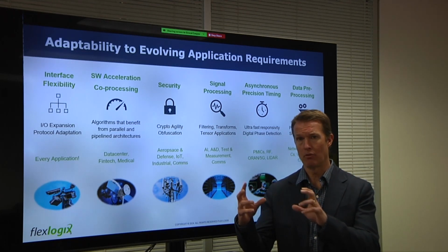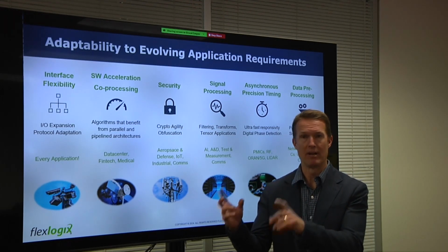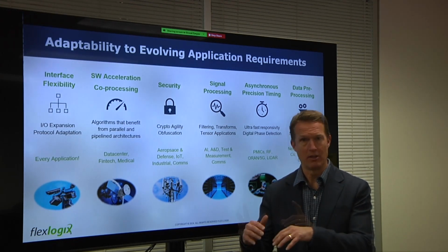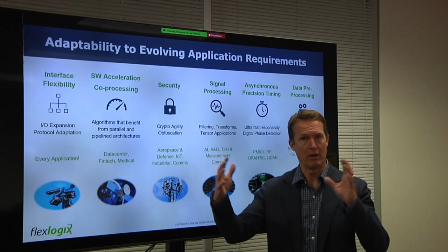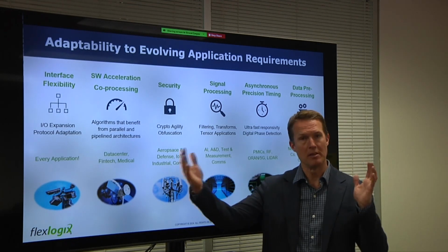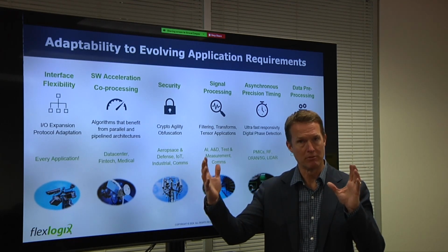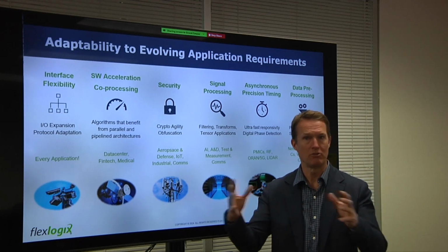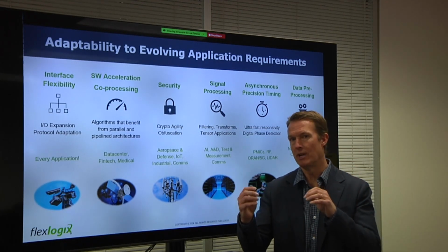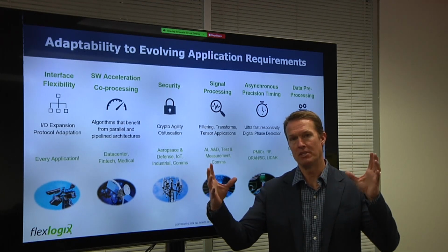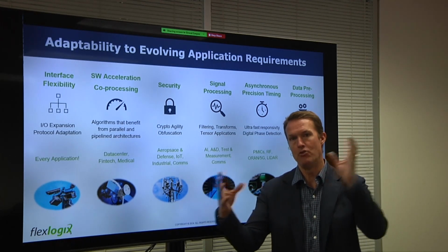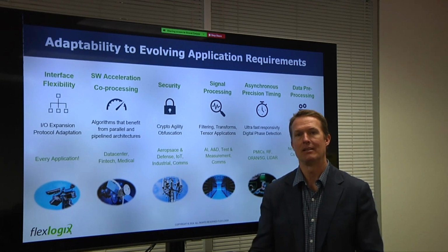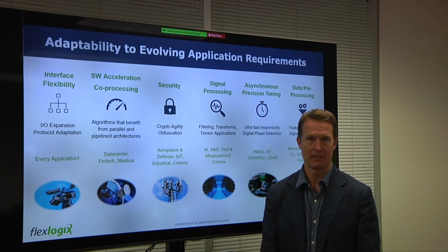Bringing that embedded programmable logic FPGA technology into your IC is critical, and everybody's design requirements are different. As I stated, larger complex algorithms may require a bigger logic array, and the scalability to provide that to a customer exists. What's really important here is that an embedded programmable logic array can scale to virtually any size you need. So you're not buying a discrete off-the-shelf FPGA of X size when you only need 20 or 30 or 40% of that. You can now scale down to exactly what your design requirements dictate.